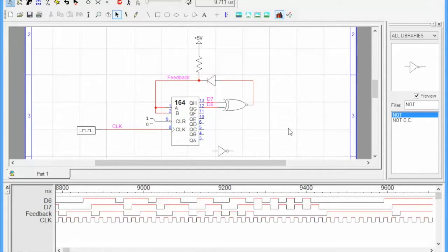And what we'll do is we'll name that guy. Okay, so let's go and get the name tool. That's him right there. And now we want to come up and click on the end of the pin. If you click on the middle of the pin, you'll be actually creating a pin number. So we'll just click there, and we'll type in D7 and then hit return.